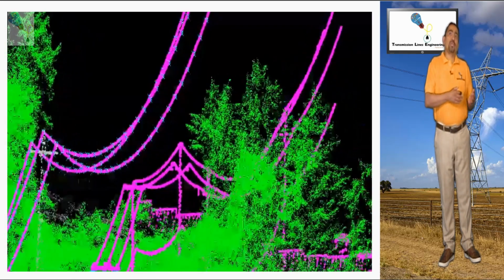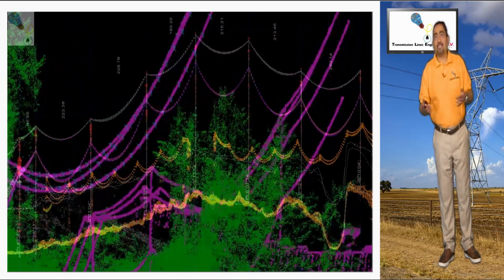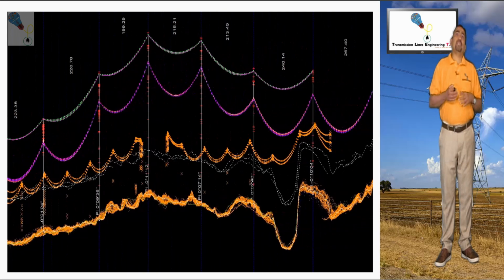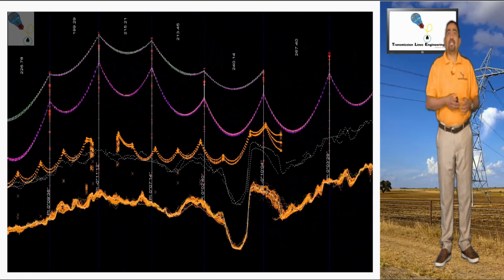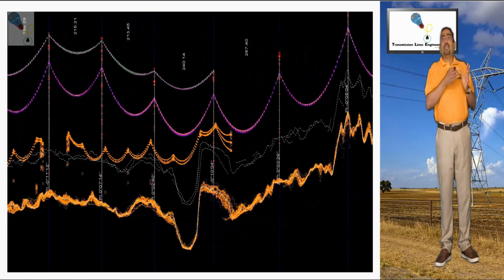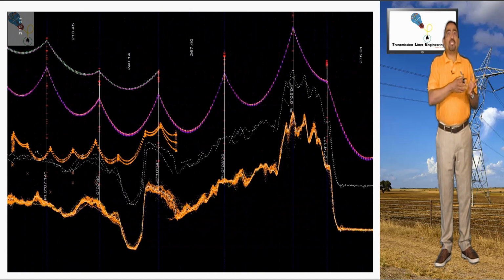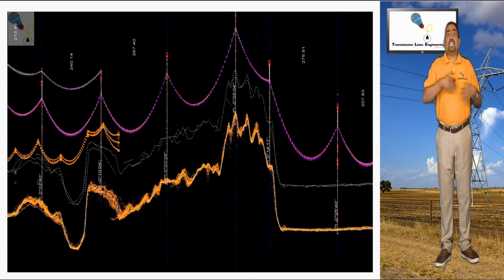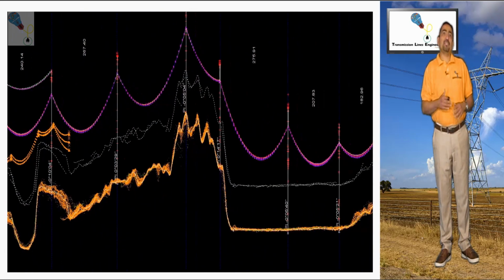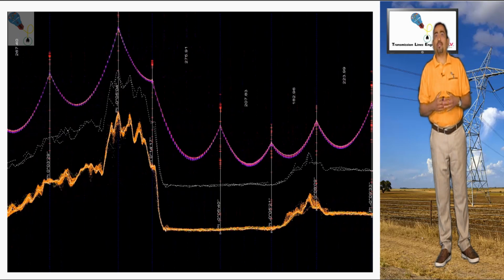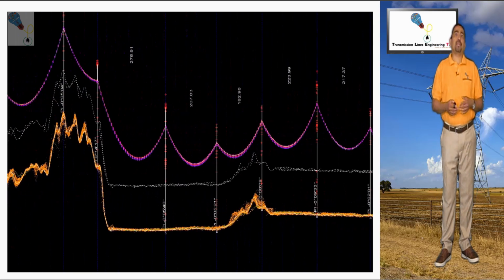In the case of working with existing lines, it is possible to obtain the attachment heights of the cables on each structure, taking into account the existing heights, including the length of the existing insulator, and it is possible to model by means of PLS-CADD.